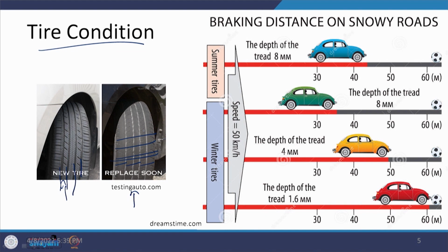If you do a study using these type of things, one study whose material I have included here, first of all defines the effect with respect to the season. So, we have summer versus winter, and the comparison has been made in terms of the tread, which is 8 mm in both cases, and how it makes an impact on the distance by which the vehicle is going to stop.